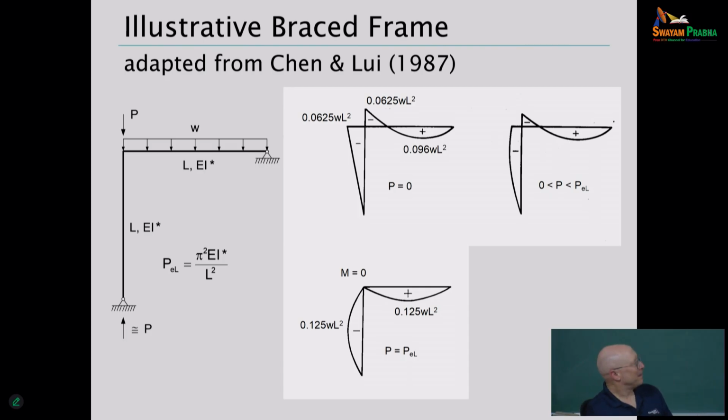So often, in a first order analysis of this frame, we say, oh, I'm getting restraint from the column on the beam. I get a negative moment at the knee. I can reduce the moment from my design of the beam. Okay, the column is restraining the beam. But then we do buckling calculations. We say, oh, the beam is restraining the column. We get a K factor less than 1, right? They can't both be true.